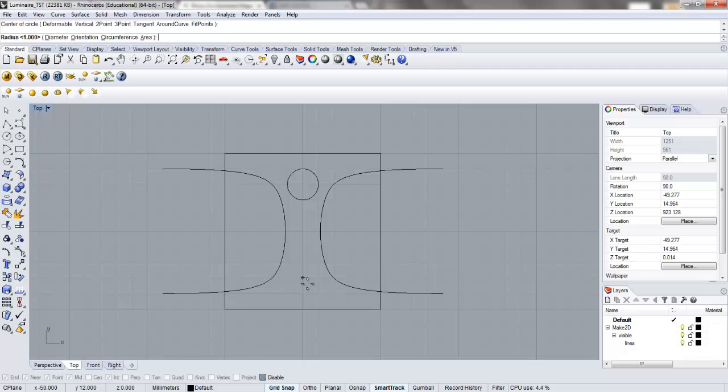Something that you guys are going to want to pay attention to is our 3D printer has a minimum tolerance for this assignment of 0.04 inches. That's not entirely accurate. You can go a lot tighter than that, but if you're going to be going tighter than that, you're going to be either experimenting with the printer's capacity to print that thin, or you're going to essentially know what you're doing. And so we'll want to make sure that you're aware of that as you go through it. At a minimum of 0.04 inches, you will in fact be able to do whatever it is you want to do.